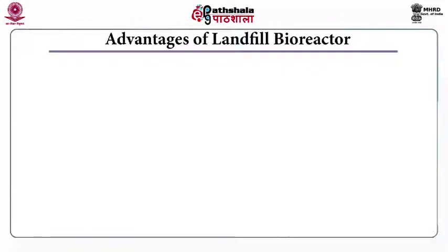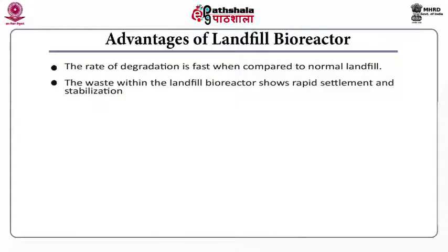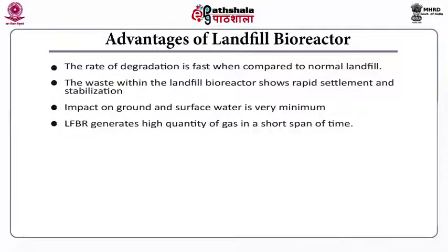Now, let us look into the advantages and disadvantages of a landfill bioreactor. The rate of degradation is faster in a landfill bioreactor than in a conventional landfill, and that becomes a major advantage. The waste within the landfill bioreactor shows rapid settlement and stabilization. The impact on the ground and the surface water is very minimal, and they generate a very high quantity of gas in a short period of time, which is again a major advantage. The greenhouse gas emissions are generally reduced, which is again one of the major advantages of a landfill bioreactor.